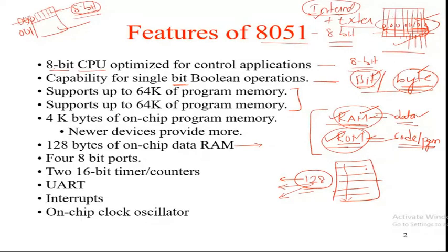That is, only a few of the addresses are going to be assigned for bit, and a few of the addresses are going to be assigned as byte. So all are not going to be assigned completely for both byte and bit addressability. Some are assigned for bit and some are assigned for byte. Some are assigned for both bit and byte addressability. Like that, the internal memory is organized. 128 bytes of RAM is there. Okay, that we will see later, how it is organized there.